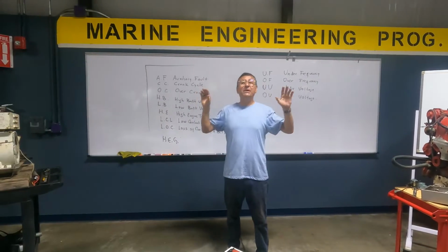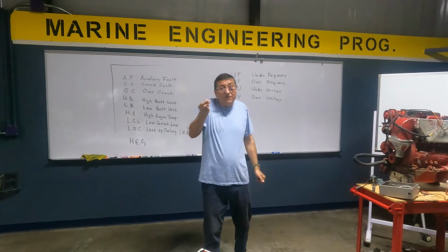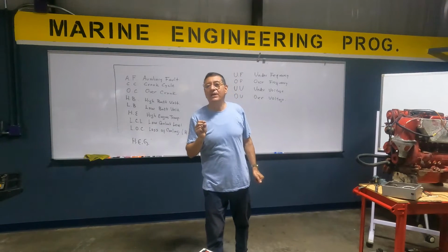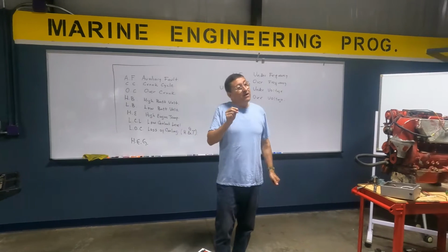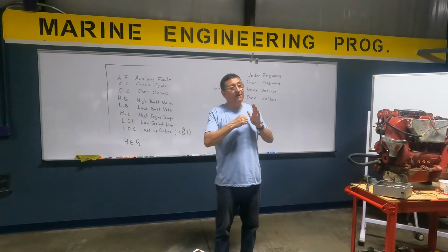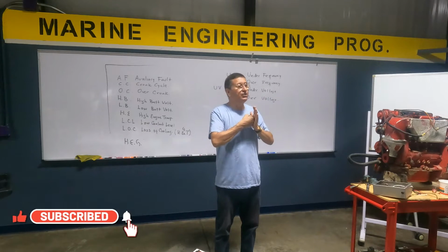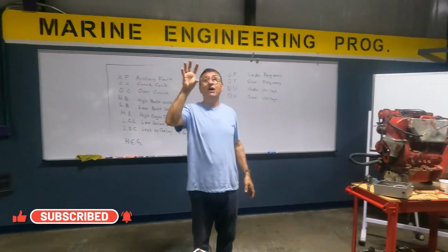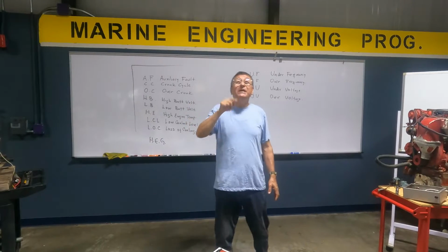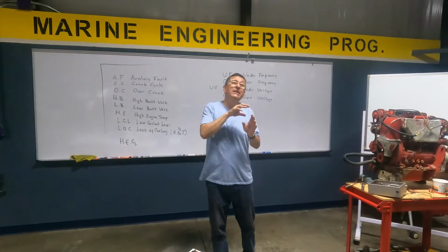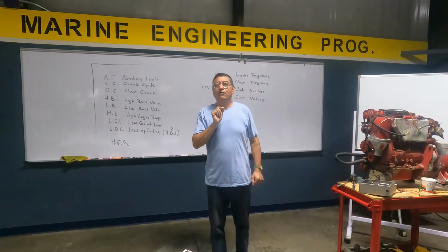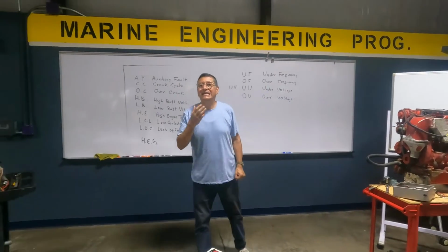When you have a temperature problem, it's because before that problem, you had a problem of bad lubrication. When you have a bad lubrication in some area, finally the metals touch. And when the metals touch, the temperature increases. And now you have a high temperature. This is because originally you have a bad lubrication over there. For that reason, my recommendation is this.